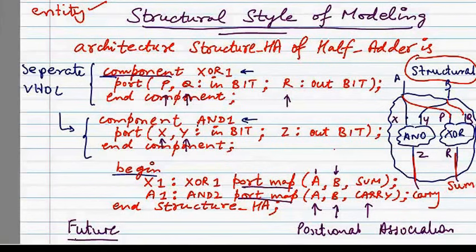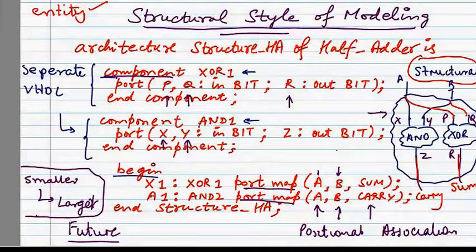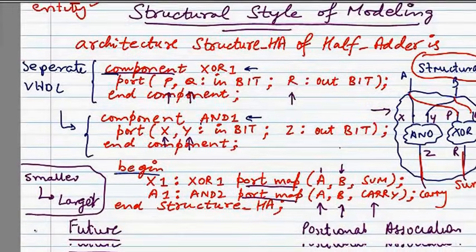So this was the structural style, where I specify the structure of my VHDL design and I write my architecture in this way. As you see, this is a much longer VHDL design, but it helps me connect smaller designs into a larger design. That is when I will use the structural style of modeling. We will see an example in a future lecture, so do not worry about this.